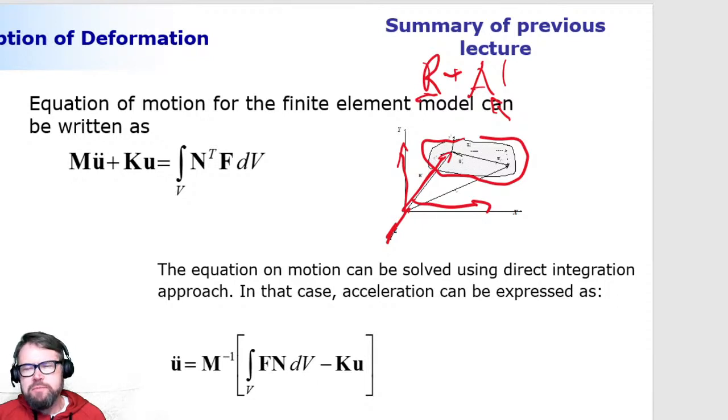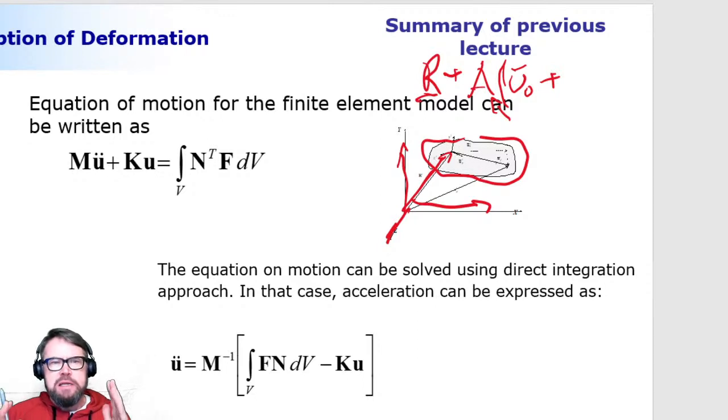Then what we describe with respect to the body reference coordinate system is the particle location, denoted as u bar 0. That is the particle location in its undeformed configuration, the configuration where there is no mechanical deformation whatsoever. And this is where we stop in the case of rigid multibody dynamics.